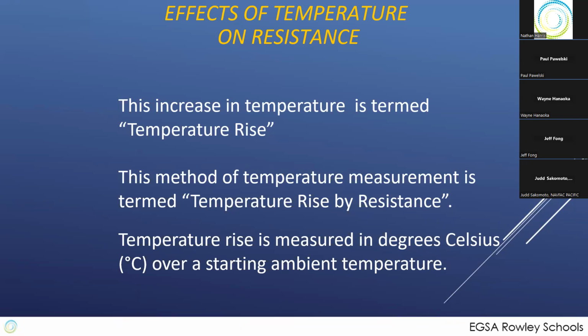Okay, we've worked out the math for it, but to actually test it, we take a generator, a whole gen set, we hook it up to the maximum rated load it's supposed to be, and we fire it up. And we run it until the temperature measurements we get everywhere on the generator are stable. We call that a thermally saturated condition.